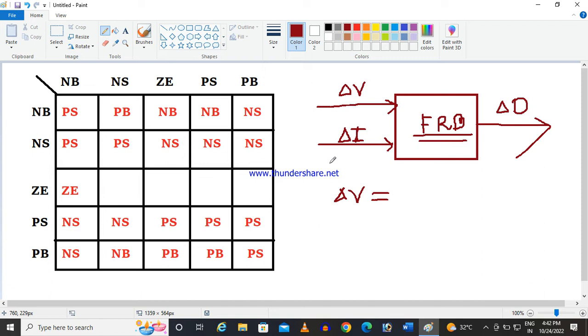Definitely you need an ADC, an analog to digital converter. Most microcontrollers use a successive approximation type of ADC, so it has its own conversion time. After capturing the value, once the conversion is completed, it will do certain calculations, which also takes some time.